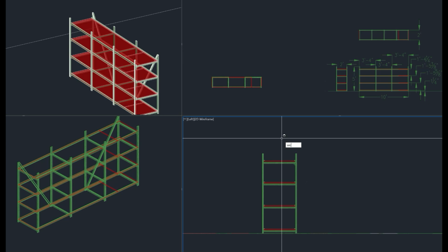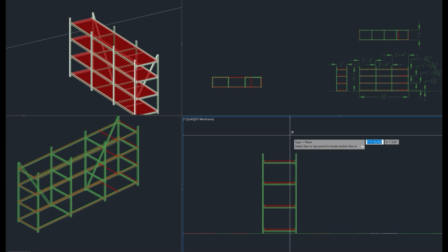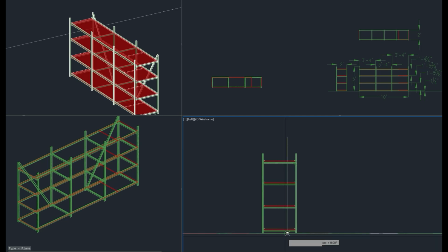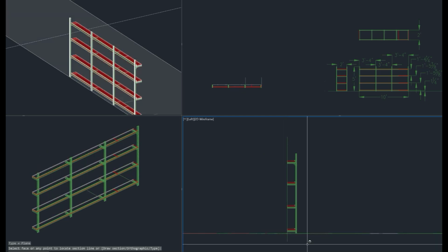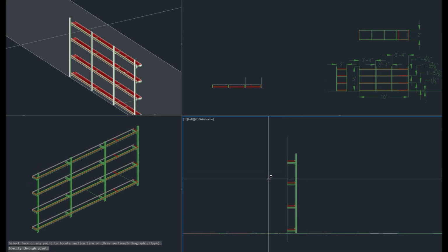Let's switch to another drawing of a unistrut rack I designed a while back. And just as a note for electrical unistrut, a piece of 3/4 inch plywood will fit exactly within the unistrut channel. It slides in very easily.